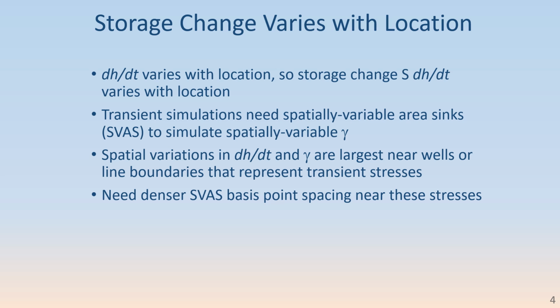The spatial variations that occur in the head derivative with time and with extraction are going to be largest near your stresses, wells that turn on, line boundaries that change head, and things like that. And you'll need denser basis point spacings near those stresses.